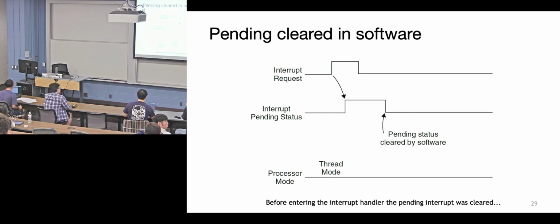There are weird edge cases that should probably be thought about. One of them is you could have an interrupt request that comes in, and now the NVIC puts it into pending status, and you could have it cleared by software. That seems like a really weird edge condition. How could software even react fast enough for that? The typical case, which we just bring up to show, is that you could have an interrupt disabled, but you've still configured it to fire off its IRQs.